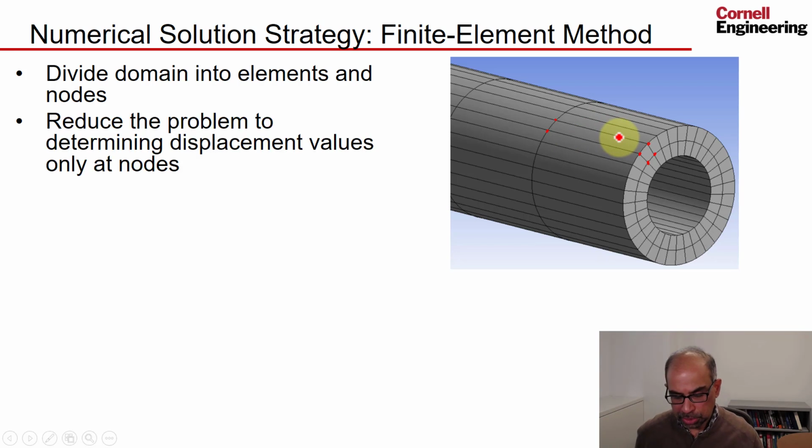And you say, hey, it's really hard to determine the displacements everywhere. So we'll determine the displacements only at selected points, which are these nodes that I marked out over here. So a big jump here from finding the displacements everywhere, finding unknown functions, to finding discrete values. That idea is called discretization. These ideas are familiar to some of you; for some others, it might be new. So this is just a quick and dirty overview of the big ideas.